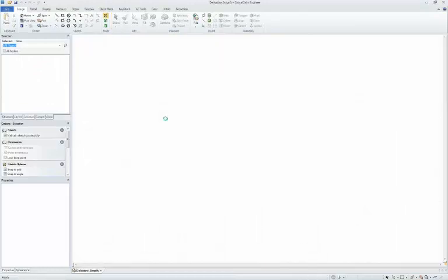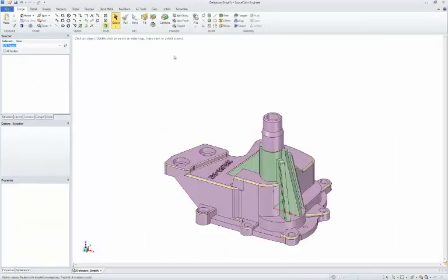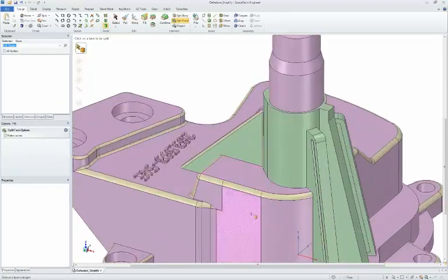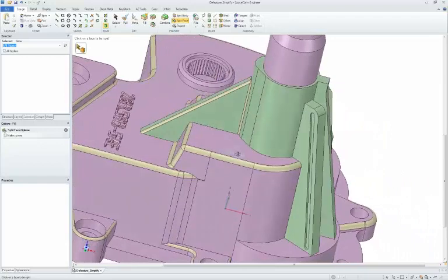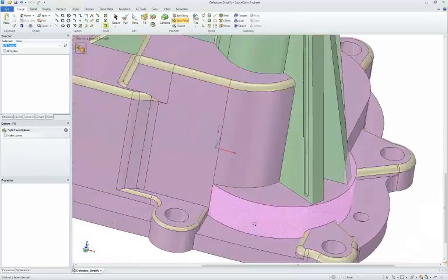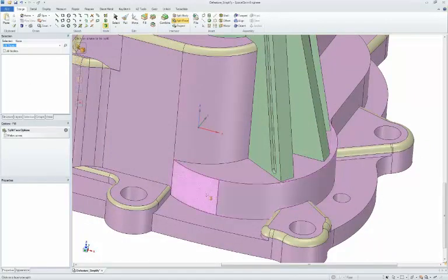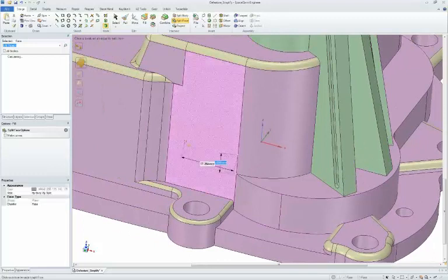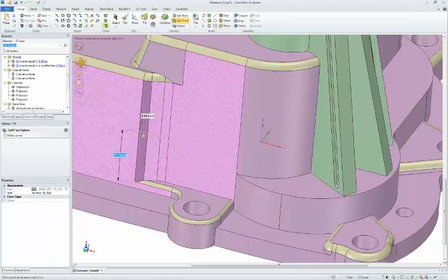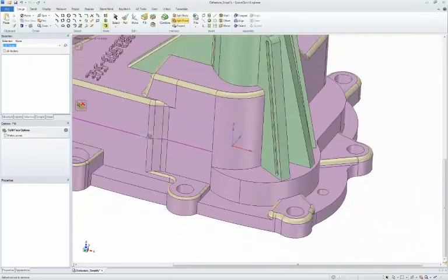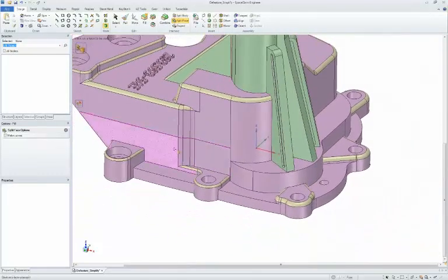But another way to create faces or split them, I would use our split face tool. I use this sometimes just to partition areas if I want to apply a force in just a small location. What it will do is let you select a face and split it into different faces, different regions. And this can be used to split multiple faces up just by control selecting them. So I can split a bunch of faces at the same time. And that's just helpful if I want to, again, apply a force to the bottom faces or use them as a boundary condition.